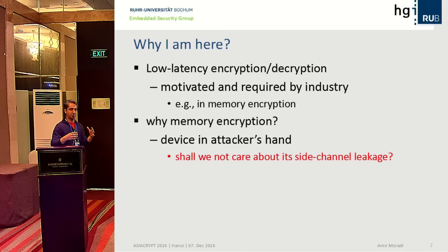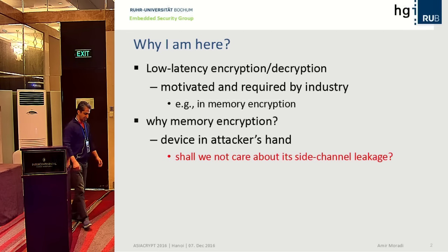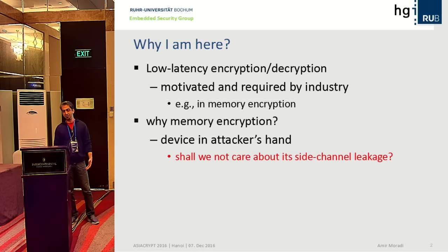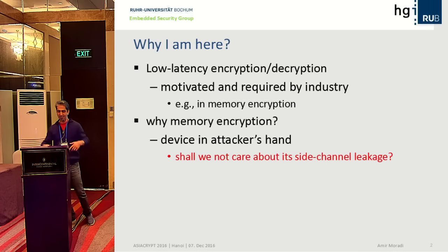Suppose you have a system on chip, a complete embedded system with a microcontroller or microprocessor that wants to save to or read from memory, but the data written to memory should be encrypted. If you stay with standard ciphers like AES, with a normal round-based implementation, it needs a minimum of 10 clock cycles. Every time you read from or write into the memory, you need to wait 10 clock cycles. Of course, that is not optimal.